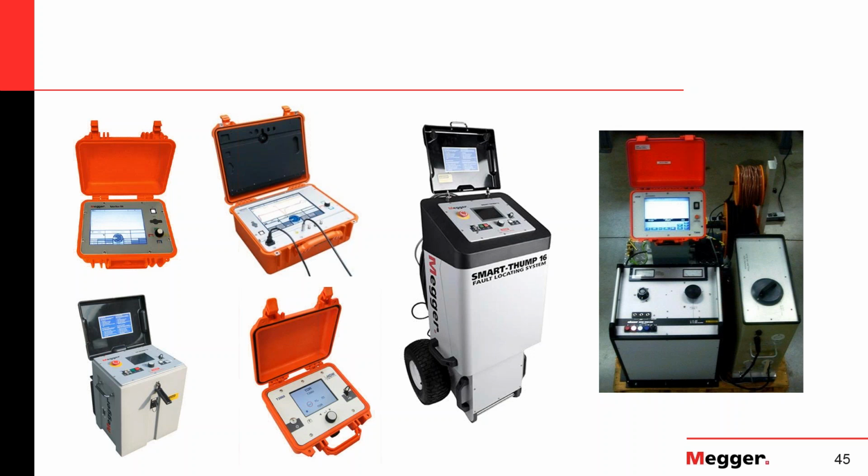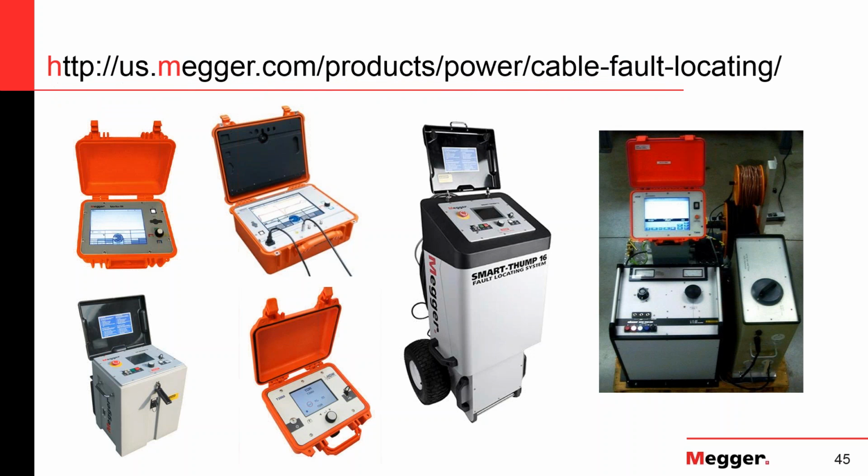And on the right, you can see a system that is probably more convenient for downtown network fault location. This is an SWG 3500, so you have a surge generator, an additional capacitor to provide you more energy. On the right, you can see the filter that was talked about for arc stabilization, and on top you can see the radar. This is a heavy, typical van-mounted system with very, very high energies that you need in those downtown networks or for PILC cables. And if you want to know more about the product line, this link will help you.